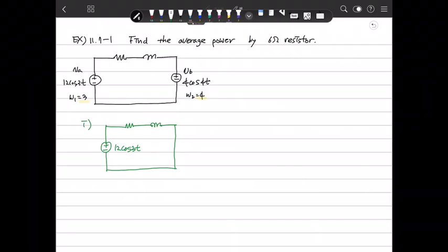So this is 6 ohm and 2 henry. The phasor is 12 at 0, and omega is 3 radian per second, so the impedance is j omega L, with omega 3 and L 2, so j6.